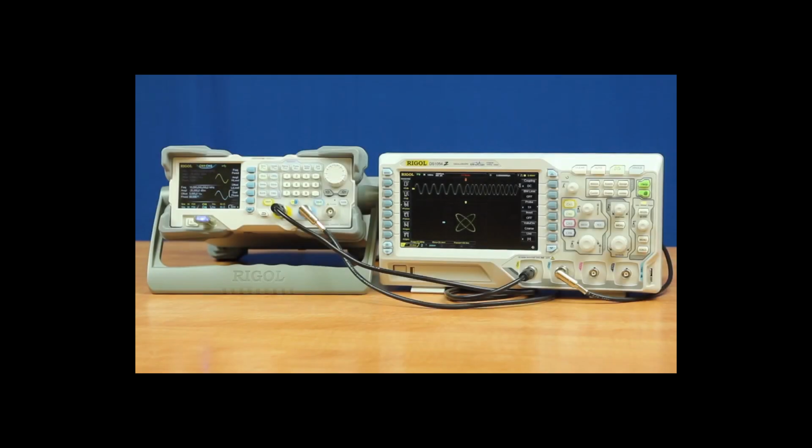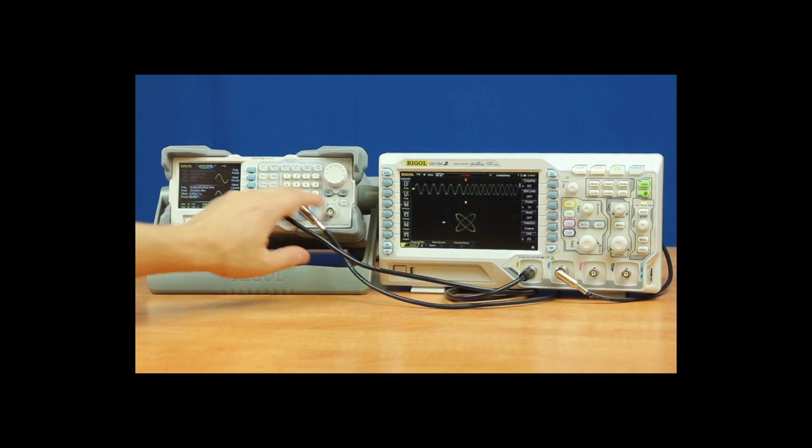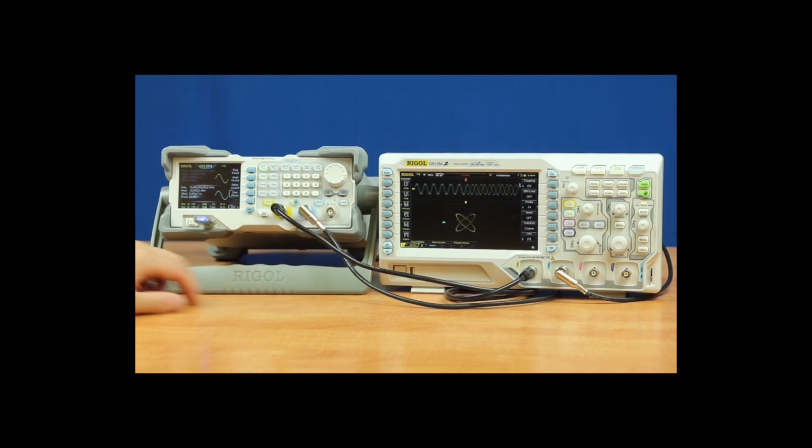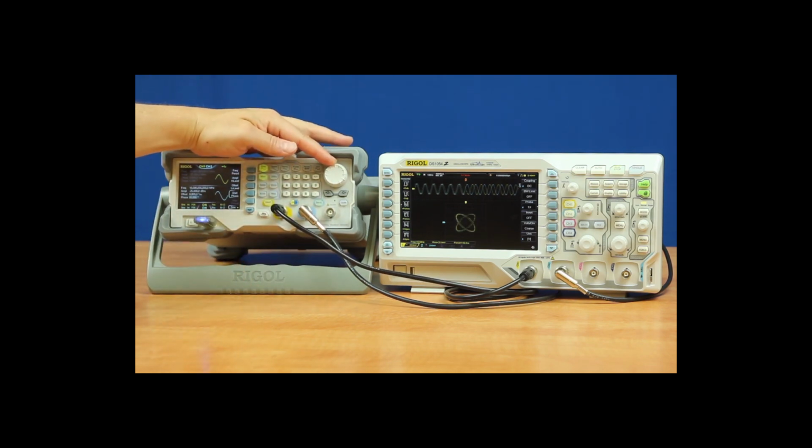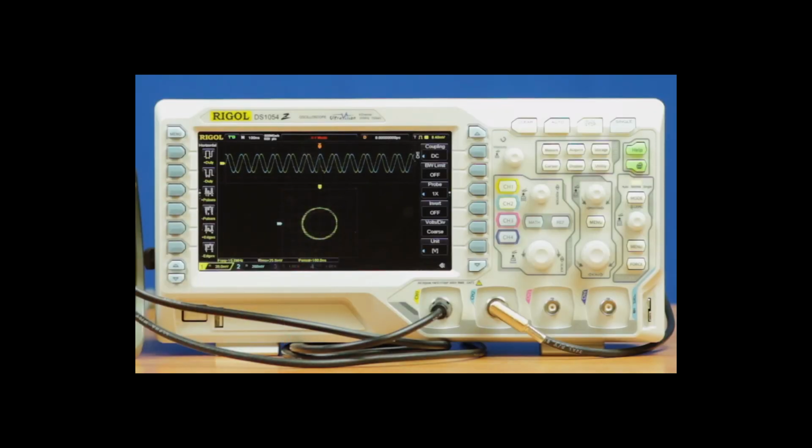So now we're looking at a phase shift key modulation. So we've used the USB stick to open our setup files on both the generator and the scope. We've turned our 2 output on. And now all we need to do is adjust the start phase on this channel here until we get really our full circle. So this indicates that we are, again, either 90 or 270 degrees out of phase between the 2 channels. That's how we know we've got these offset in the correct amount.